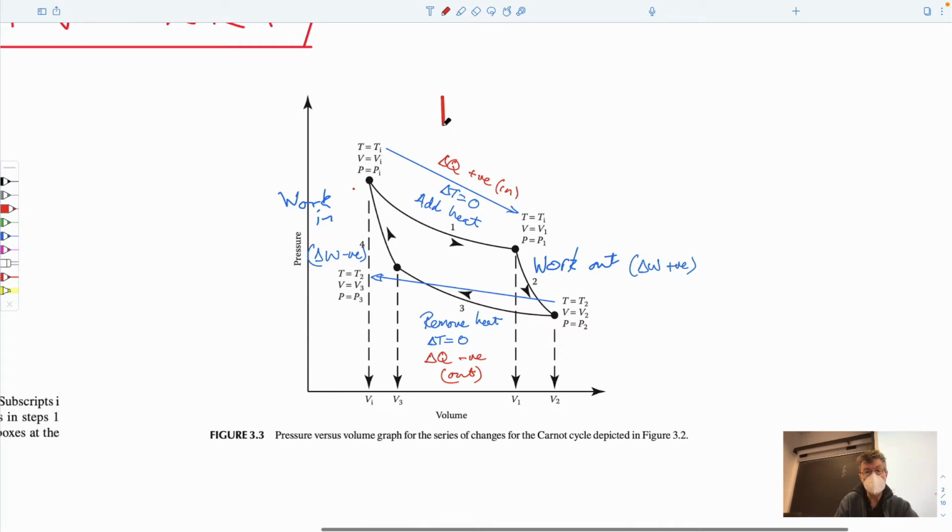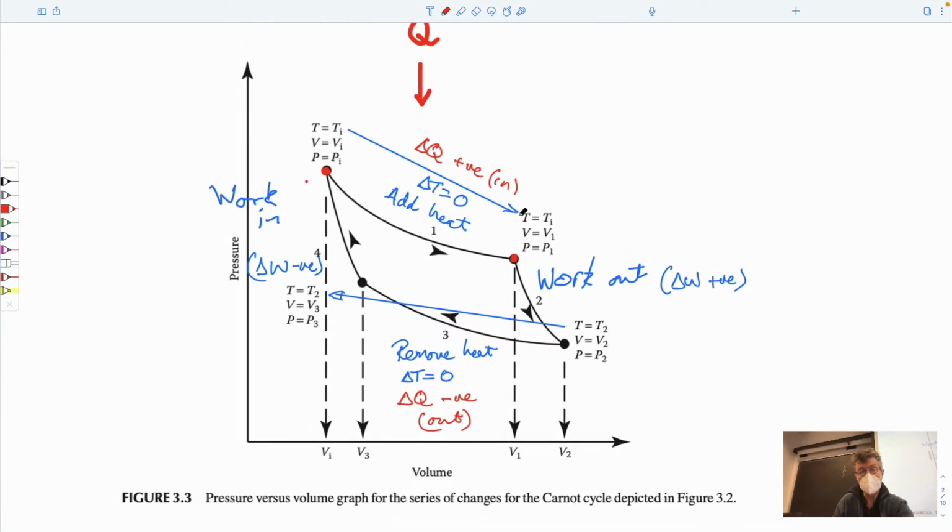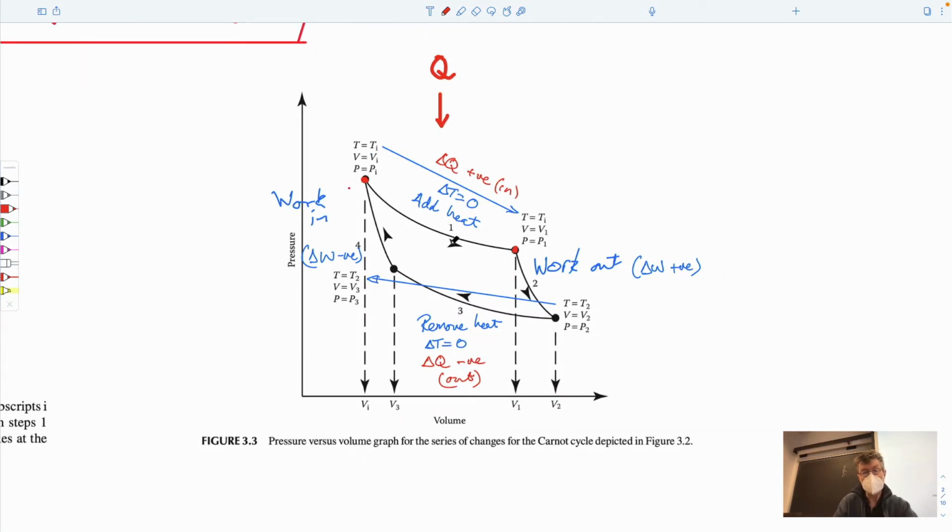This is the thermal energy that's going into the system to the turbine. It's changing phase from a liquid to a gas at constant temperature. Temperature is not changing as you go from one to the other. And so this thermal energy in is driving an ability to now pull work out of the system, because now the volume has changed. You've gone from a relatively small volume to a relatively large volume because you're allowing it to expand as it vaporizes. That expansion is able to drive a turbine, and that turbine is allowed to take work out of it.